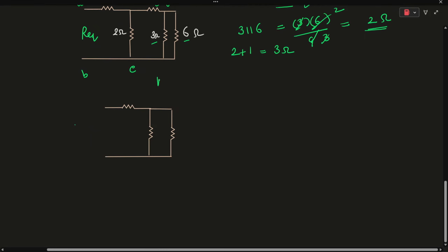It means that this will be the simplified version of this particular electrical circuit. Okay. So this is the 10 ohm, this is your 2, and this is the 3 ohm resistor. Since the 2 ohm and 3 ohm are both connected in parallel with each other, the equivalent resistance will be 2 into 3 over 2 plus 3. So that is equal to 6 upon 5, which is 1.2 ohms.